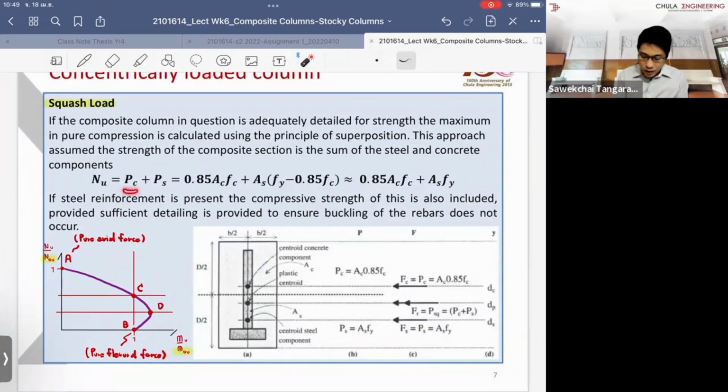And in this formulation, let me explain what they discuss here. It is the combination of the full axial capacity you can have from the concrete and the full capacity you can have from the steel, right? The concrete, as I mentioned before, they adjust the concrete strength. It depends on the material you're looking at. If you look at the encased section, meaning the concrete envelopes the steel section, you drop the concrete strength by 15%.